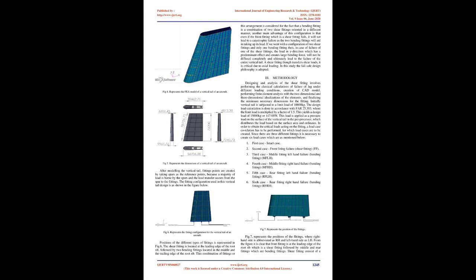The vertical tail of an aircraft plays an important role since it controls the yawing motion of the aircraft, and it's seen in all commercial aircraft, except for some fighter aircraft adopting the delta wing construction. The vertical tail of an aircraft experiences different types of loads when it is in air, or during takeoff, or when it's taxiing. It experiences the maximum loads when it's in the air and performing a maneuver. A typical vertical tail for a 17-seater aircraft is as shown in Fig. 4.